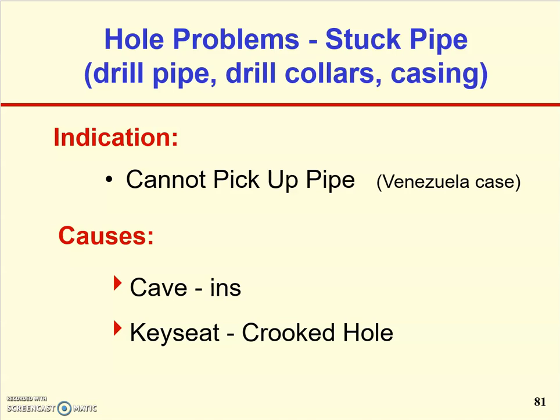So there are other issues such as stuck pipe, where the pipe is stuck down there, you can't take it out, and you're trying, for example, to do a trip, right? You want to take everything out, and then your pipe is stuck down there, you can't remove it from the bottom of the wellbore, and a lot of issues might happen. You can go ahead and read about the stuck pipe yourself.